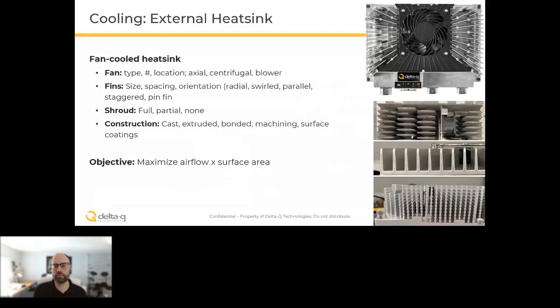Your heatsink needs fins, so what's their size, thickness, and height? How are they spaced? How are they oriented? They can be radial, which is what you're seeing in the top right. They can be parallel, as you're seeing on some of those lower chargers. They can be swirled so that they follow the direction of the rotation of the fan.